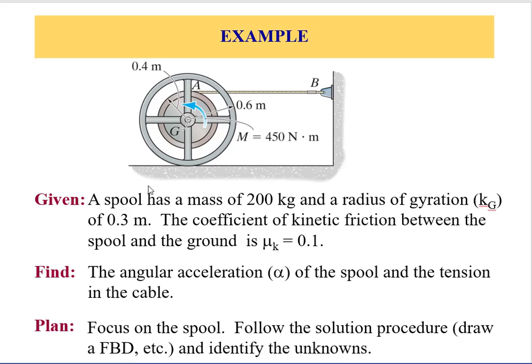So that's one equation. And because of that, it will slip anyway. It will slip as a result of that torque. And therefore, the friction force, F, is going to be equal to the normal force multiplied by mu_k.